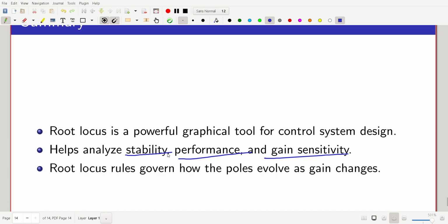Because gain changes, of course the poles are going to shift somewhere. So we need to change the gain appropriately. In a practical scenario with an analog controller, we require a potentiometer to set the gains. Now we are going for a digital controller, where in software we can generally do the tuning. But if you change some gains, it means we are changing the poles from a control perspective.